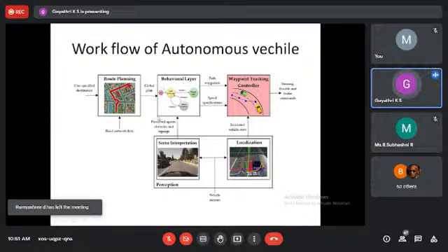In addition to that, every fraction of a second I have this information given by radar. Every fraction of a second, I am populated with that information. What your system is doing is finding out where the vehicle is in that particular second, who's around me, and what the other agents are planning to do. With that information and this route planning, which is called a global plan, the global plan is the overall path my vehicle will take to reach the destination.